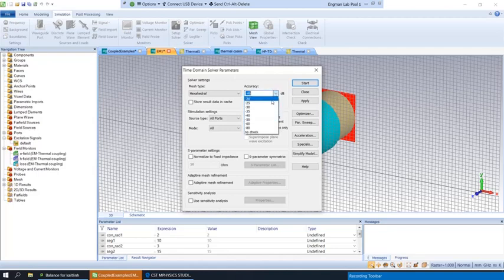So they take their accuracy down a little bit to make the simulation run faster. So just know that the simulation will be less accurate. In addition, they don't perform adaptive mesh refinement, which means, again, the accuracy of this simulation is going to suffer. But where we're just demonstrating this as an exercise in how to do a coupled simulation, we don't really care.